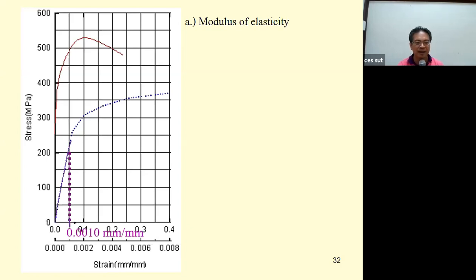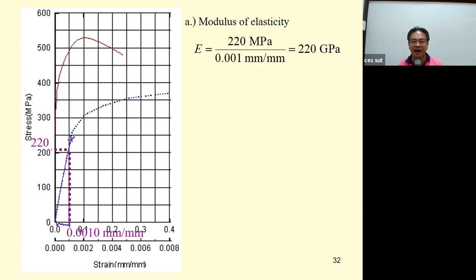So we expect the strain as 0.01, and it is still in the linear elastic. So we find the stress. Divide the stress by strain, you get the modulus of elasticity. And then for the proportional stress, you use your ruler and draw the line. Just draw the line. At the point that the line just separates from the curve, that is going to be the proportional stress. You may estimate this one to be about this point. This is 250. So you may say this is 255.